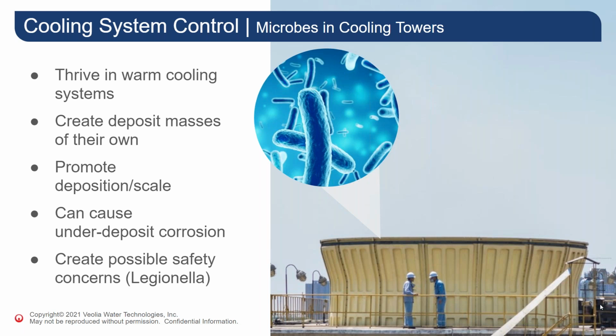Certain bacteria can wreak havoc on the cooling system. Slime producers secrete biofilm that captures debris floating by, leading to poor water flow, deposition, and corrosion. Sulfate-reducing bacteria can hide in the dark portions of the cooling system, and they use sulfate in place of air for oxygen and secrete acidic sulfides into the biofilm, which corrodes the metal surfaces that they're affixed to. And lastly, any biomass in the water becomes a breeding ground for Legionella.